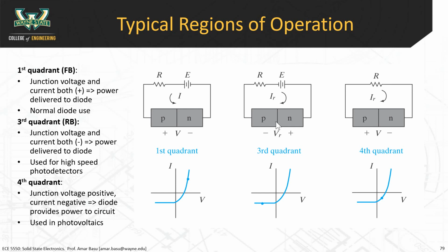If you reverse bias the diode, the diode typically only conducts current in the forward direction. You just get that very, very small reverse saturation current, unless you go over the breakdown voltage. Correct. So this is how we're biasing the diode.